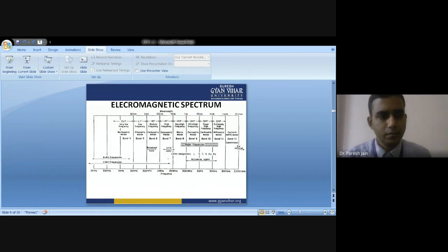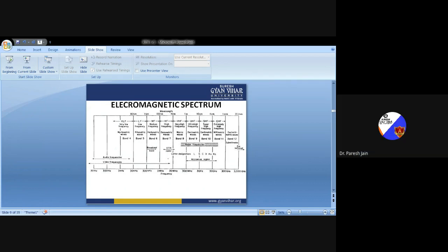Next are the types of radar output displays. A scan is used for gunfire control and accurate range information. B scan is used for airborne and fire control range and bearing, forward looking. E scan is used for altitude measurement, and the PPI type was already discussed in the previous lecture.